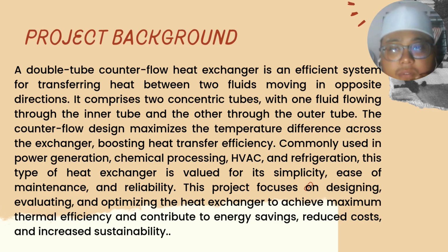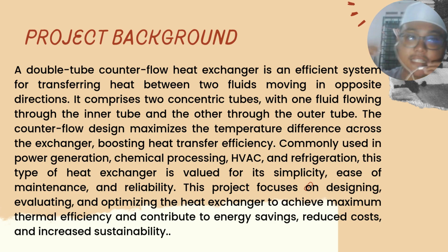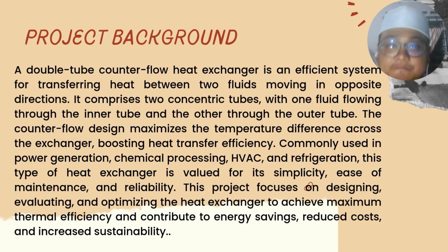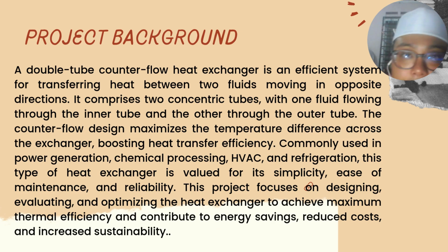The counterflow design maximizes the temperature difference across the exchanger, boosting heat transfer efficiency. It is commonly used in power generation, chemical processing, HVAC, which means heating, ventilation and air conditioning, and refrigeration. This type of heat exchanger is valued for its simplicity, ease of maintenance, and reliability.